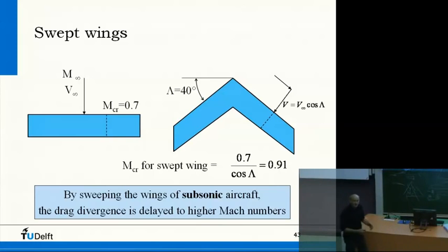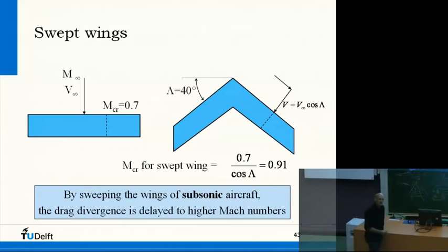It's even detrimental, because delta wings have a low aspect ratio. And if you have a low aspect ratio, then of course your induced drag is higher. So for a subsonic aircraft, you just need a high aspect ratio for a low CD induced.